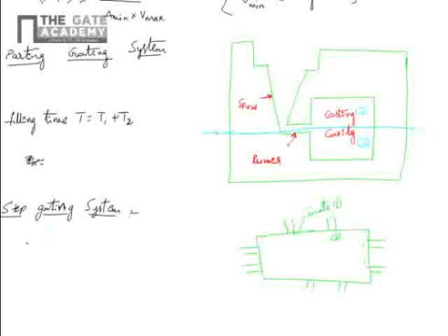So here the time required, the pouring time or filling time, is equal to the volume of casting divided by N into A minimum into velocity Vmax, where N equals the number of gates. Generally they ask only the top and bottom gating systems. They didn't ask parting and step gating systems. So this is about the gating system and the pouring or filling time calculation.